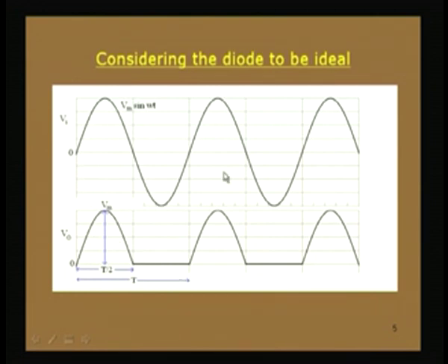It is the input waveform, which is an AC waveform. So, it is V m sin omega t, the expression for that AC waveform, because we all know that this is the well known expression for a sinusoidal voltage waveform. Omega is the angular frequency, which is equal to 2 pi f. F is in cycles per second or hertz, and our domestic power supply has 50 hertz as the supply frequency, meaning f will be 50 cycles per second or hertz.